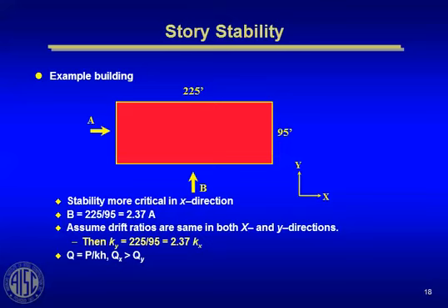of the building. It had moment frames in the long direction that were designed for drift, and it was such a soft building that it had a serious, very serious P delta effect, to the point that when they ended up fixing the glass and fixing the foundation, they came back and stiffened the frame, and at the same time they put a tuned mass damper on top of the building that Bill LeMessurier designed to control perception of motion in the top floor of that building, because it was so soft it was very sensitive to acceleration under the high wind loads that you can get in Boston sometimes.